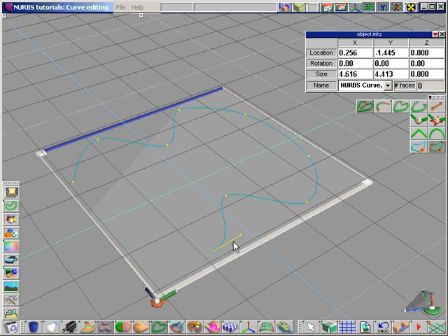Yellow control point handles are visible, attached to selected control points. One handle for open curve endpoints and two for all others. Control point handles are used to change the shape of spline segments. Handle length is proportional to the amount of change that it introduces as you move it to alter the direction of a spline segment, very similar to pen tools in illustration programs.